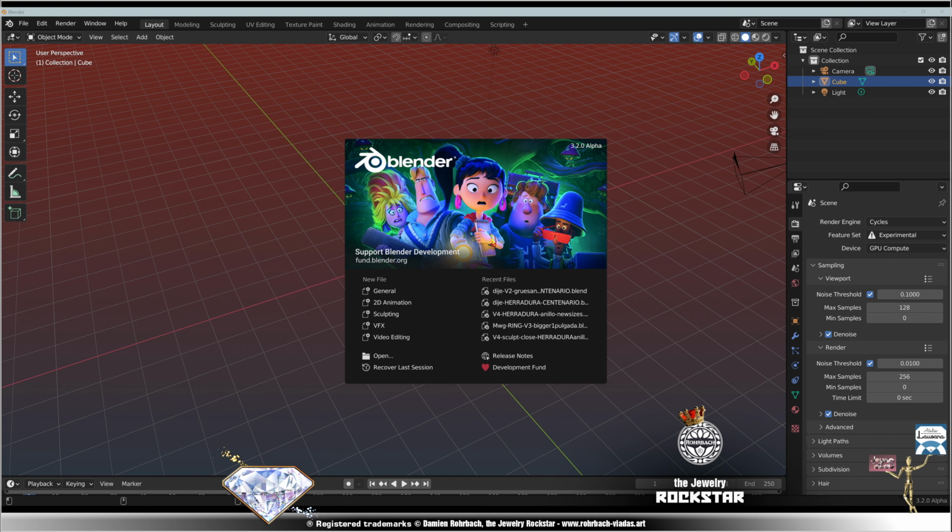Let's go to edit mode, Alt Z, here's the circle. Extrusion on the Z axis, F to close, Control I to invert the selection. Okay, let's be precise here at the level of the fillet of the stone. Extrusion on Z, S. About here it's fine. Easy. Let's go down here.